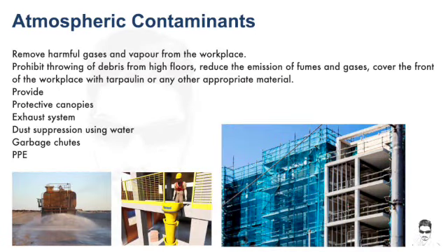Remove harmful gases and vapor from the workplace. Prohibit throwing of debris from high floors. Reduce the emission of fumes and gases. Cover the front of the workplace with tarpaulin or any other appropriate material. Provide protective canopies, exhaust system, dust suppression using water, garbage chutes, PPE.